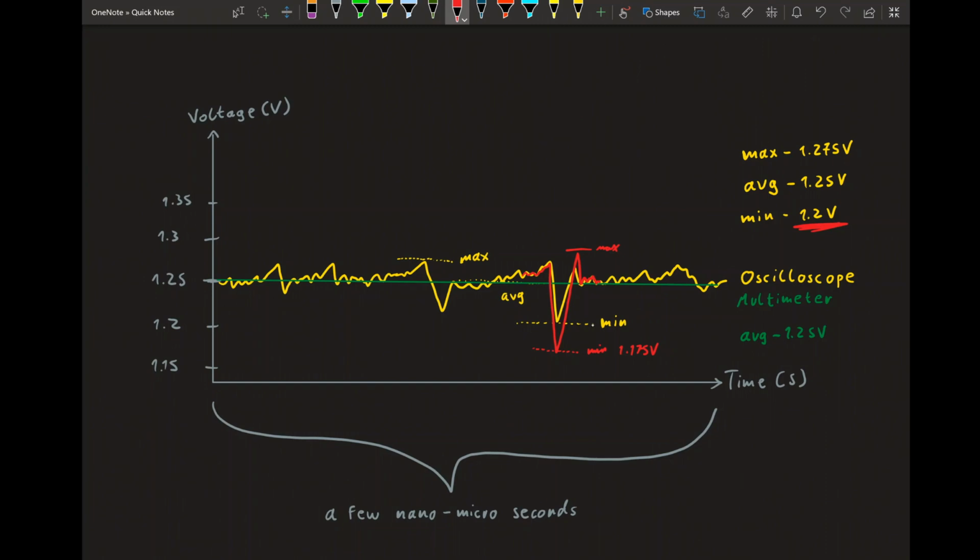And yeah, that's what it's about. That's the theory part done. The only thing you need to remember is that your multimeter and hardware info sensors are fine. They show you an average, but they cannot show you those very small deviations which happen. Transients do happen all the time. That's just how physics works. You cannot get rid of them, you can counteract them with higher end VRM design. And our oscilloscope will show us which VRM design is the best.